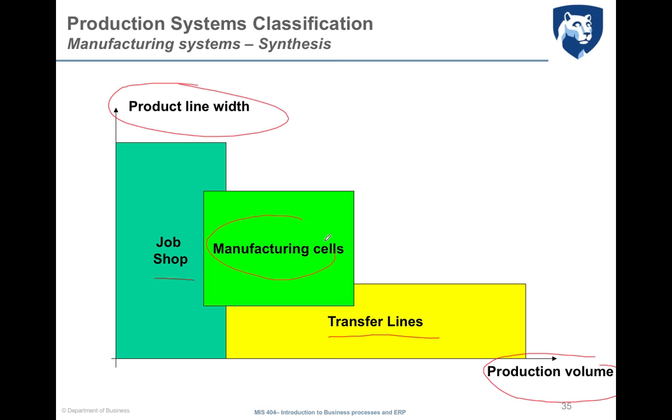In hybrid situations, so when we have relevant but not super high production volume and large but not super large variety, manufacturing cells represent the best option, as they are also able to guarantee some system flexibility in case some reconfiguration of the system is needed, so making the cell able to produce other models of product and vice versa.